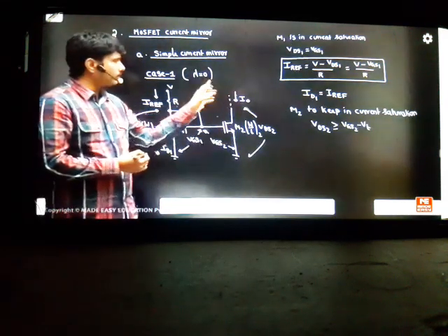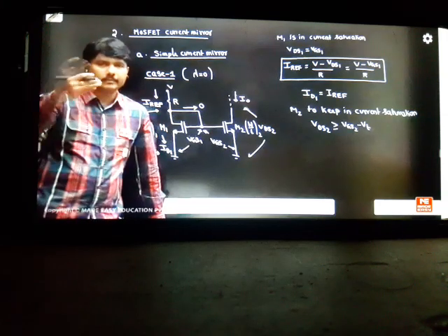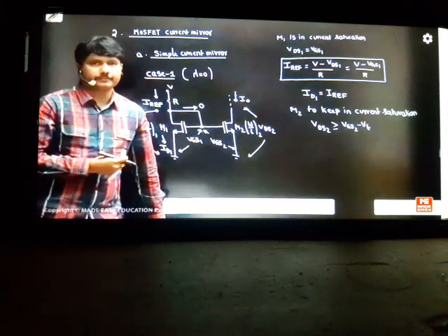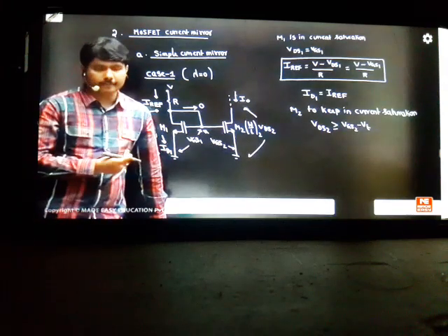This will be covered in the coming classes, because this voltage depends on the top circuits. Whatever you are designing in future, in VLSI designs, you will have some circuits here. The circuits have to be made in such a manner that whenever the drop comes here, VDS2 should be more than VGS2 minus VT. Then automatically that also will be in current saturation. Okay? That is the story.